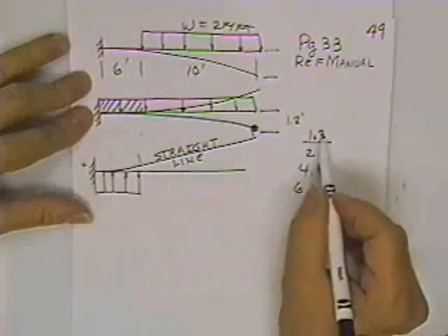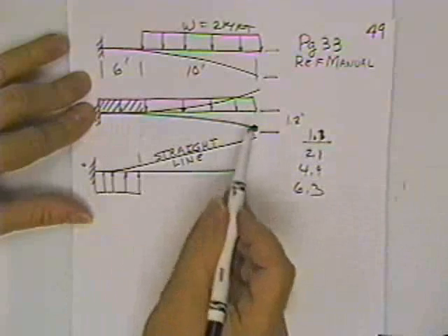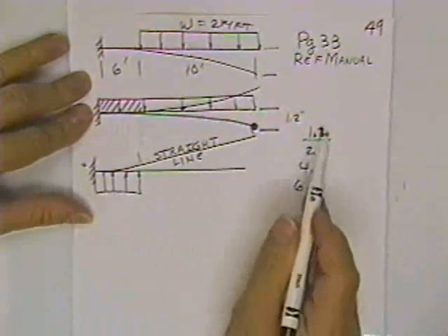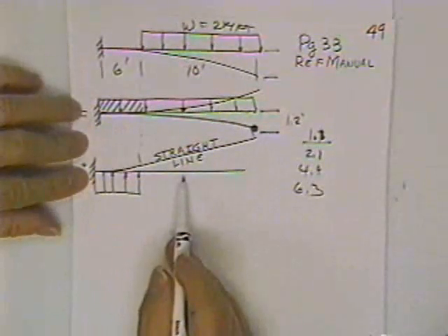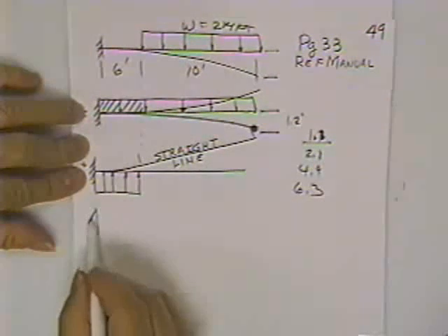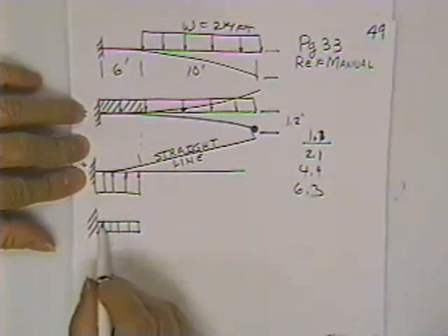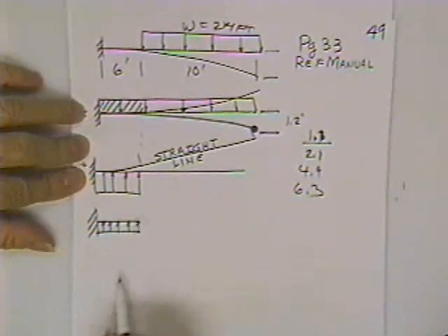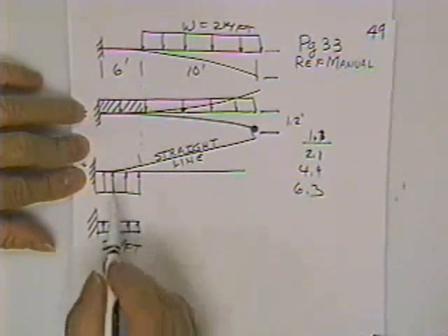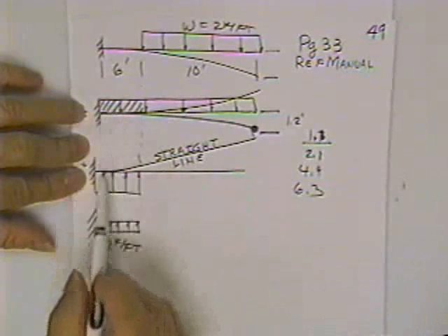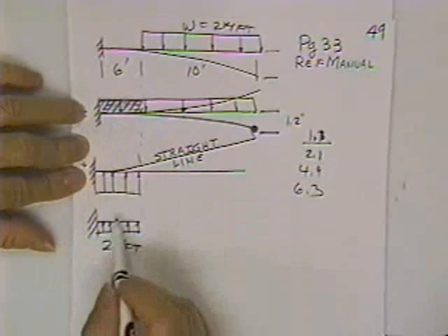Because when I take this load, now let's see, I might have to put something else here, say 1.1. Because if you take this little piece off, the thing ought to back off a little, and there aren't any other choices any smaller than this one. However, you can still get it, because what you do is you merely add this case right here. You add another beam with the load pushing up and put 2 kips per foot on it, and that means that the 2 kips per foot you put on here that you didn't want, you canceled with this here.